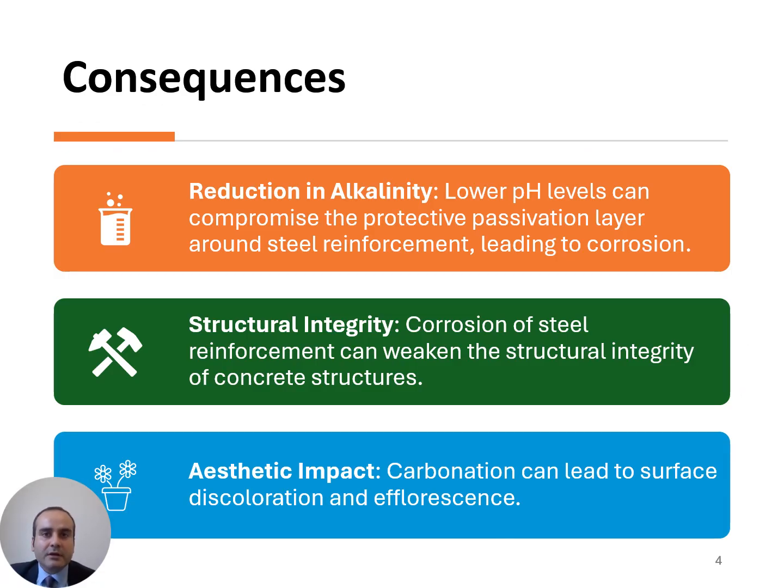Carbonation reduces concrete's pH from around 13 to below 9, compromising the protective oxide layer around steel reinforcement and leading to potential corrosion. This corrosion can cause structural damage as the expanding steel cracks and spalls the concrete, increasing maintenance costs and reducing the concrete's service life.